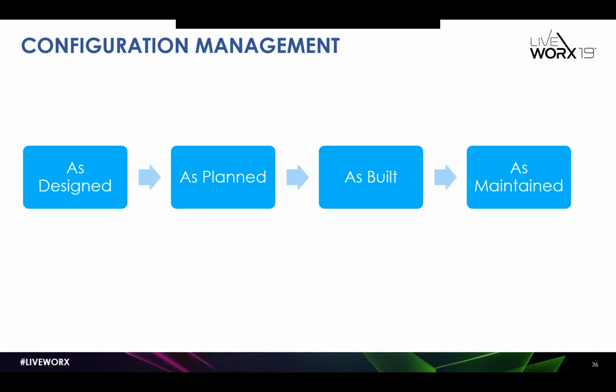As you're heading into a build for one of your products, sometimes you know that there are systems you plan for that aren't ready yet. For example, sometimes on Amazon Prime Air, we'd start building a drone before certain avionics or mechanisms were ready. If you're making a change to the as-planned configuration before you start building, that's a deviation. Sometimes during the build, you find that something gets built not to specification, but it should still be fine to operate. Changes to the as-planned configuration that happen during or after the build are captured in waivers. These deviations and waivers are known as variances, and the variances and engineering change requests that happen during a build result in the as-built configuration.